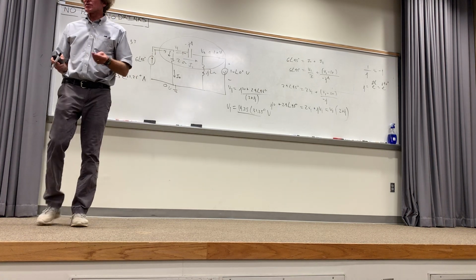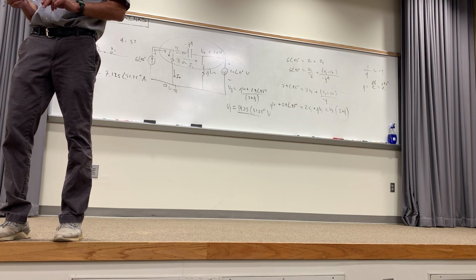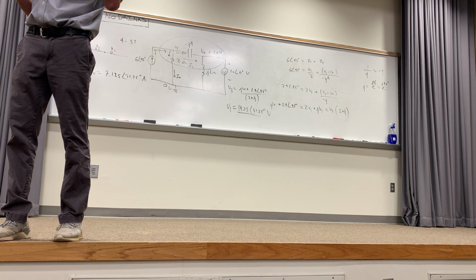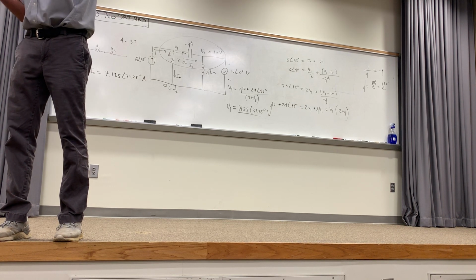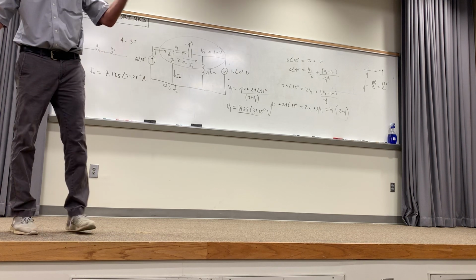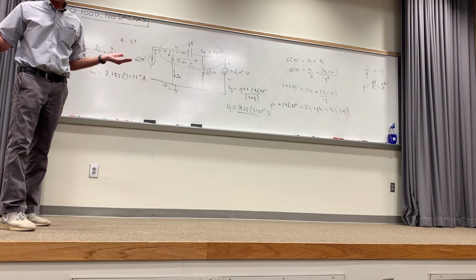The ground system, remember, voltage is between 2 points, right? So I'm going to pick one point and make it 0, and every voltage is measured with respect to that. The reason I do that is in the equations, I don't have to keep having V1 minus some 5 volts, because I put 5 volts at the ground, at the point where I'm calling ground. You always make ground 0, it reduces the mathematics, the level of complexity of the math. That's the reason to do it.